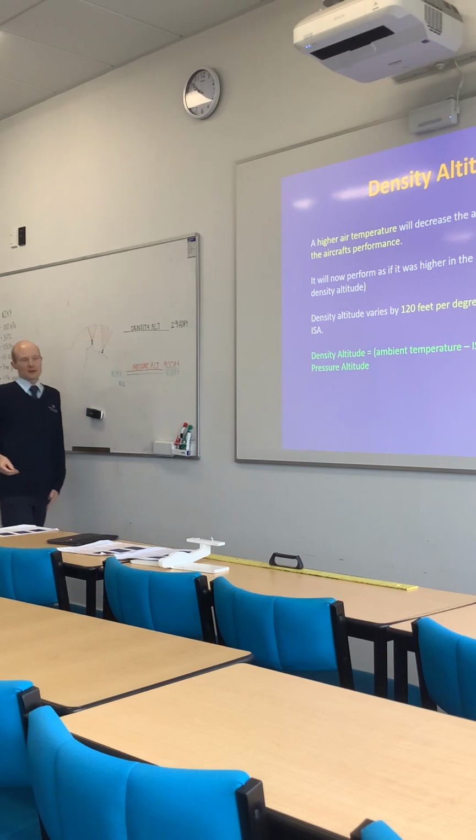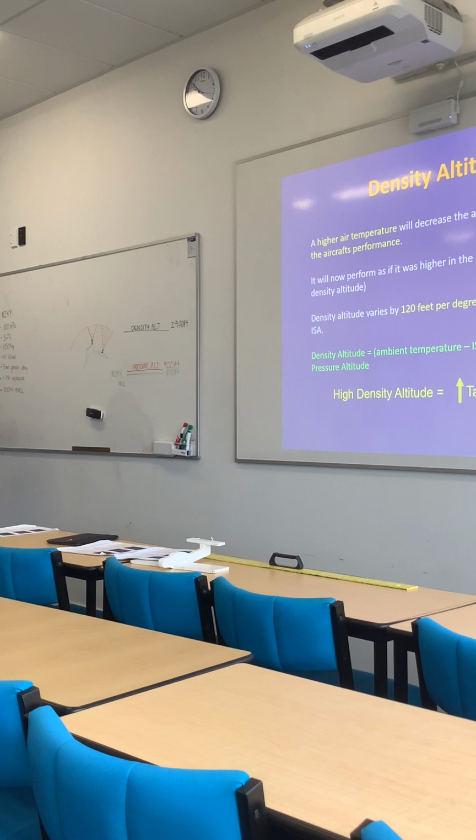When we're actually using our P-charts, we don't have to calculate this density altitude part. We do have to calculate a pressure altitude though. The graph automatically takes into account or calculates the density altitude for us. So we'll have a look at that part now.